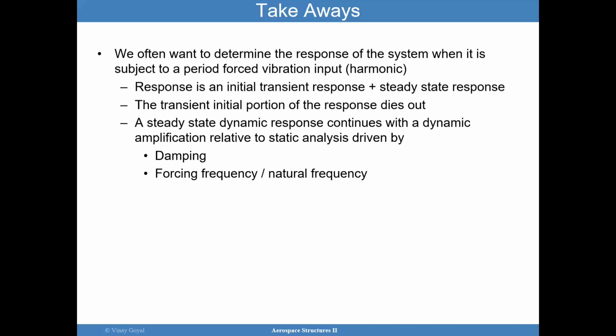And it is here that we had Pavel come in and demonstrate for us how to deal with that. But the bottom line is, when the forcing frequency is very close to the natural frequency, it can impact the amplification, and it can increase it quite a bit. Damping, however, can decrease the amplification.